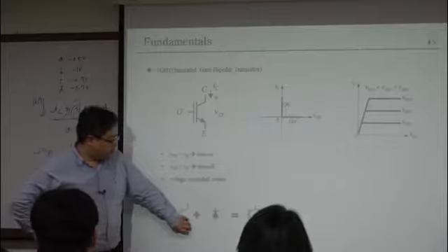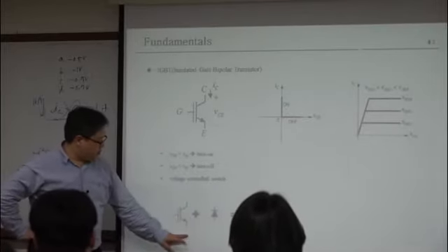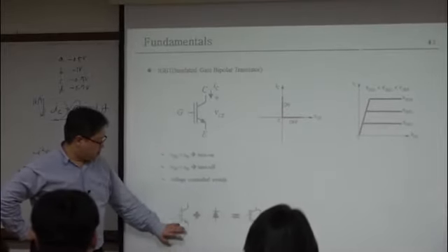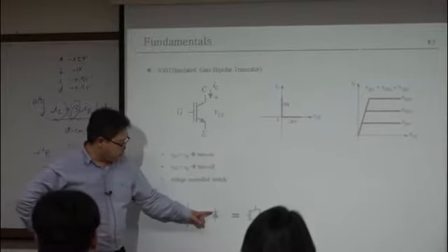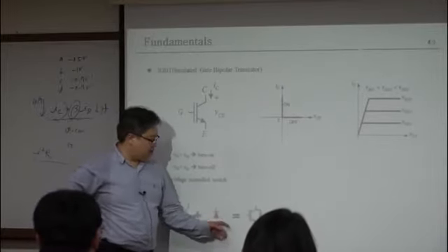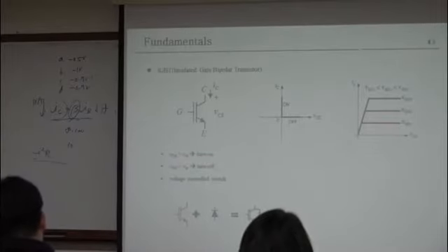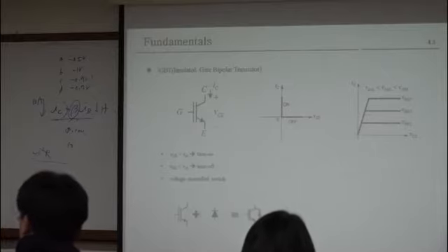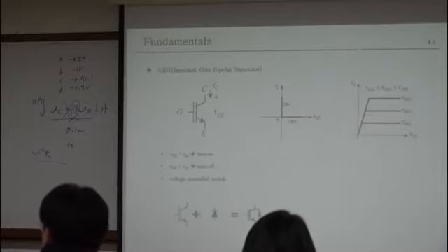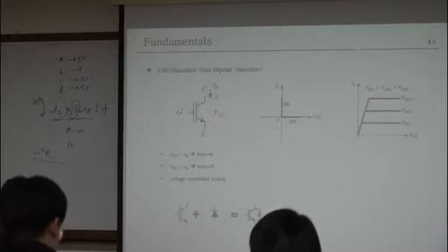So to make a reverse current flowing capability, you should equip an anti-parallel diode like that. Some IGBT include the anti-parallel diode, but some IGBT do not have the diode.